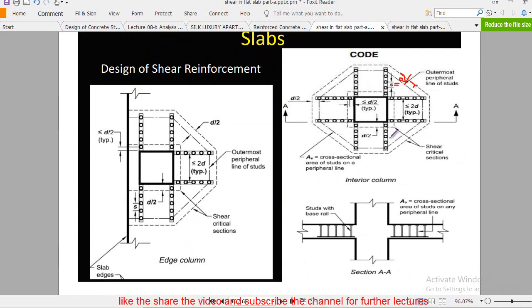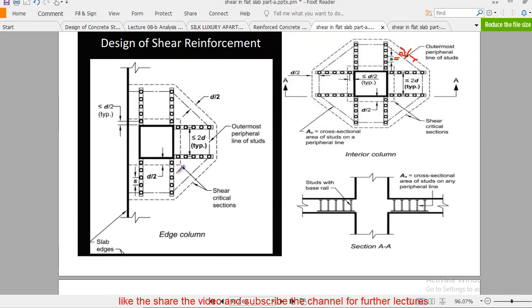And the next is the arrangement. You see here for an interior column, for an edge column, I already explained these things. The first stud should be placed at a distance of less than d by 2, and then the center to center distance. Remember, let's say for example this column side is 12 inches, then you have to place 2 rows, because you have to fulfill this criteria.